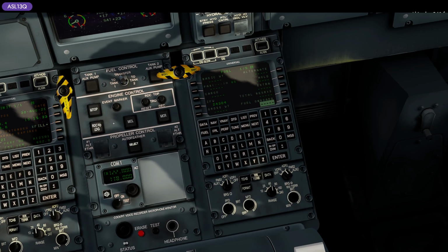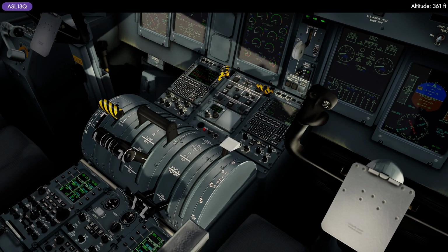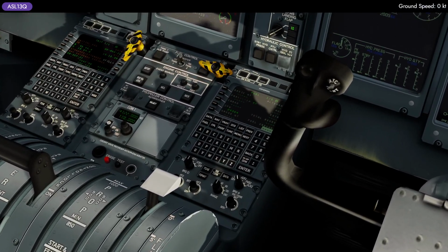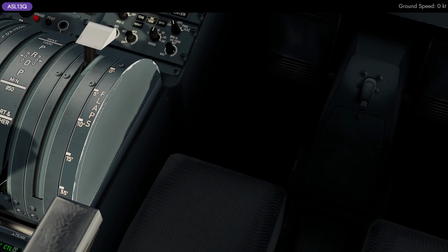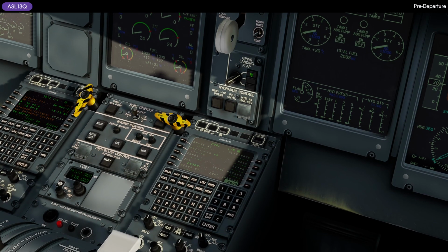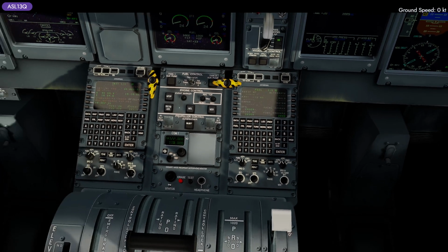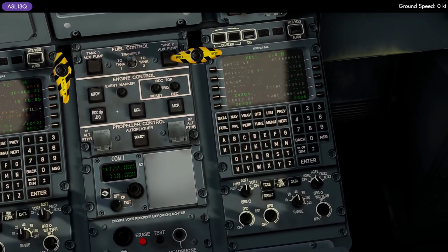And as for the fuel on board, as we already checked, we have 2005 kilograms of fuel. Let me get this out of my way for now. So 2005 kilograms of fuel. Enter. That's it. And we get our gross weight of 26,309. We'll need that later on for the speed charts. For now, everything is okay. So we'll continue with this.